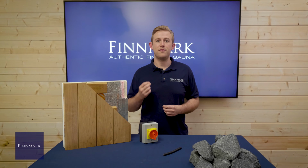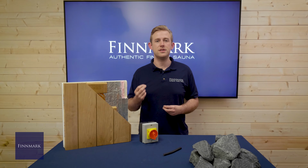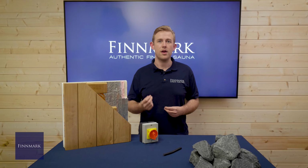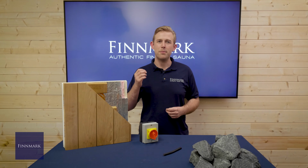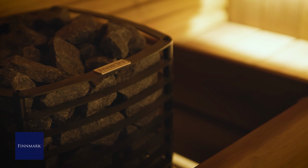The electrical supply for most UK saunas will either be a UK single-phase 240 volt supply, where you can specify up to a 9 kilowatt heater, or European-style 400 volt three-phase power supply. On three-phase, sauna heaters go up to about 33 kilowatts, which is for a large commercial sauna, but typical domestic saunas are going to be between 6 and 12 kilowatts.